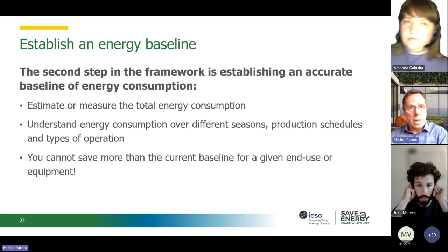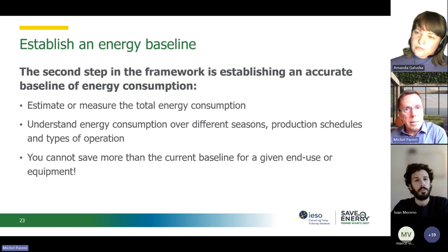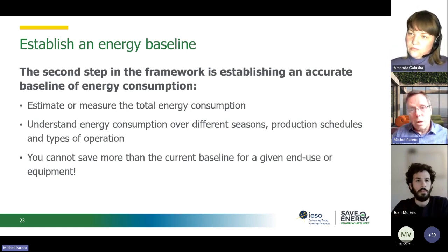You should establish, as step 2, the energy baseline. The good news about the energy baseline is that whatever method you use to establish it, you're probably going to use to evaluate the energy savings from the measures you're going to propose. It's very often the same. There are times where the method or tools are not the same, but it's very common to have the same. So it's kind of two birds, one stone when you establish the baseline.